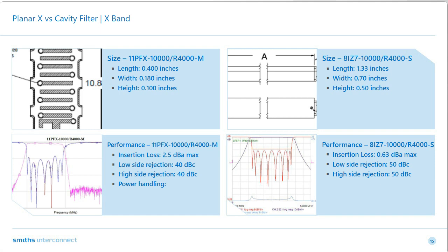A theme you will see throughout the typical standard microstrip filters is that they will struggle with ultimate rejections when compared to the cavity filters. This is due to the inline nature of most printed filters. It is difficult to isolate inputs and outputs along with different resonant sections within the filter.